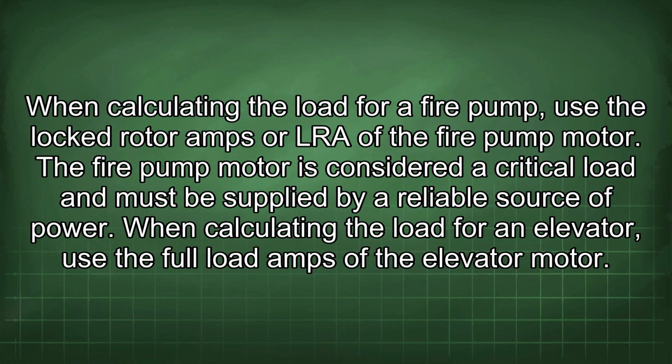When calculating the load for a fire pump, use the locked rotor amps, or LRA, of the fire pump motor. The fire pump motor is considered a critical load and must be supplied by a reliable source of power.